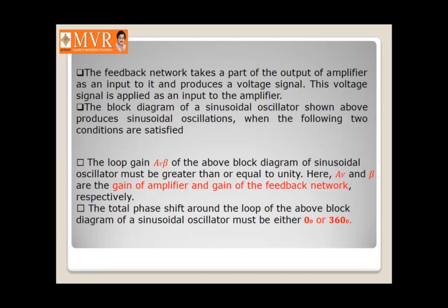As we have discussed this concept in our stability of op amp in second chapter, there the op amp is going to produce the sustained oscillations when loop gain becomes greater than 1. So there we are going to keep the beta value less than 1 for eliminating the sustained oscillations produced by the operational amplifier.